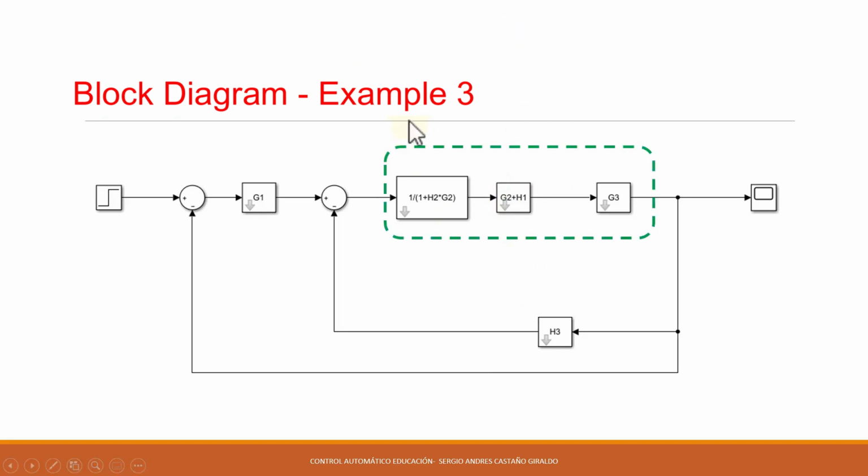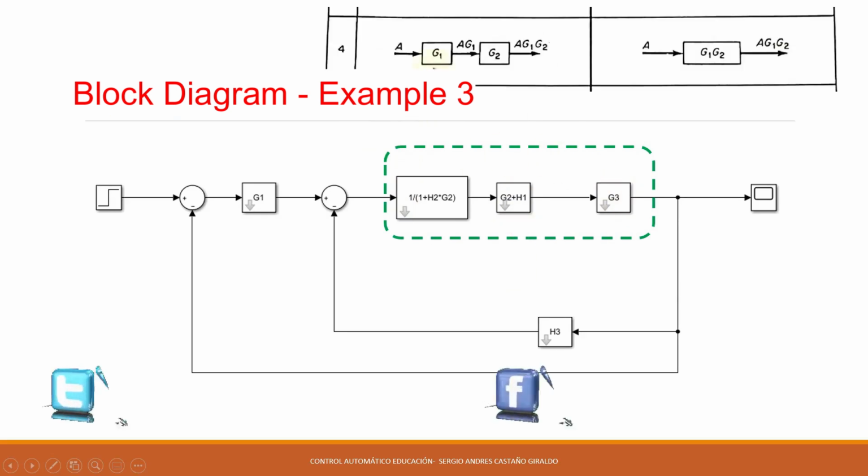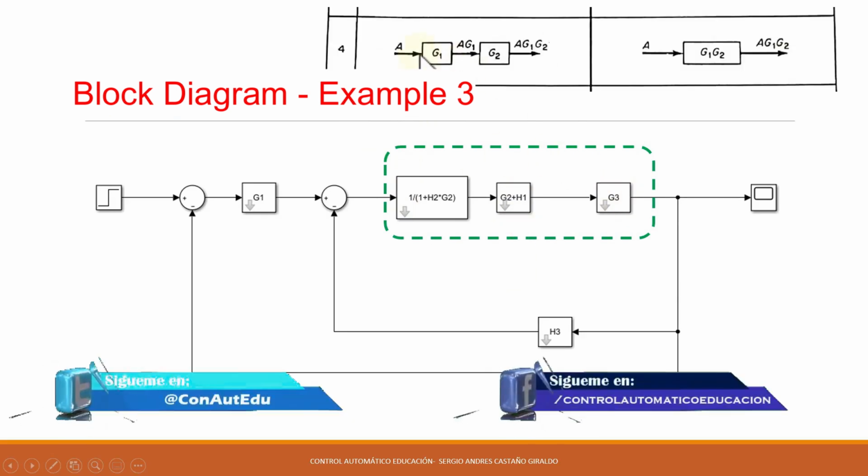So let's move on to these three blocks that are in series. Once again, we can apply concept number 4, which is that all blocks in series, I can simply combine them into a single block by multiplying them together.